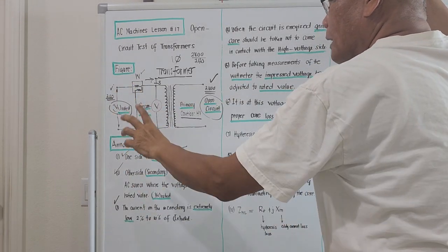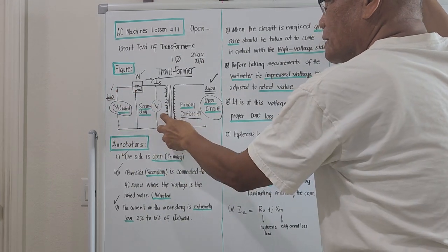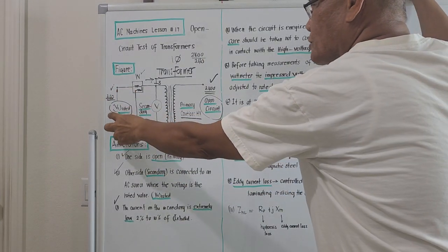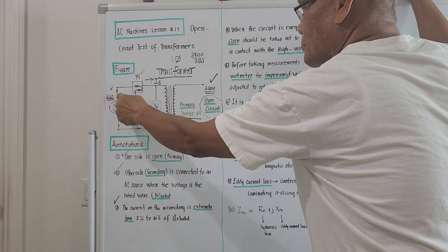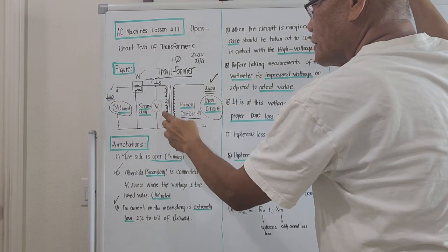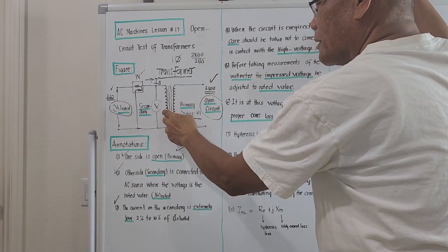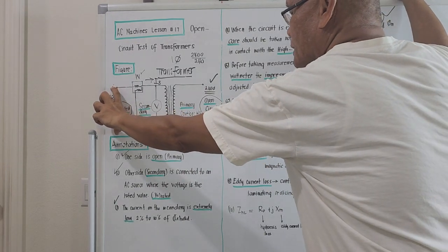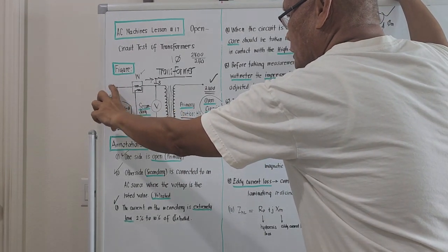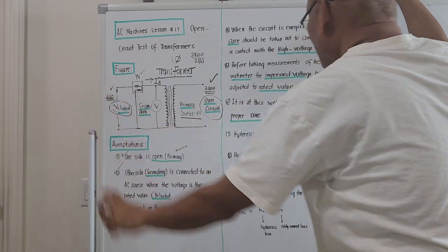Okay? How come you know it's 240? There is a voltmeter here. So if there is a rheostat here, you adjust the voltage to 240. As soon as the voltage becomes 240 over here, stop injecting the additional voltage. It will be only up to 240.